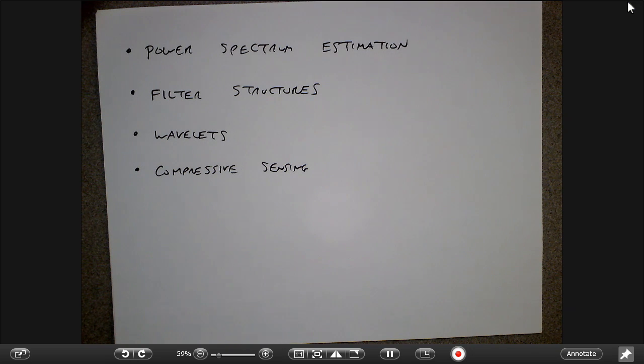to this idea that a signal may be, the way I think about it, is that there may be a basis where representing that signal is very sparse, right? So right now we take n numbers in the time domain, we convert them to n numbers in the frequency domain, and most of the time, you just get n different numbers, right? But it would be great if you found a way to represent that signal so that you took the n numbers here, and when you did the transformation, you got maybe like 3 really big numbers and then a whole bunch of zeros, right? So there's some special world where if you move that signal over, you find out that it's actually very sparse.